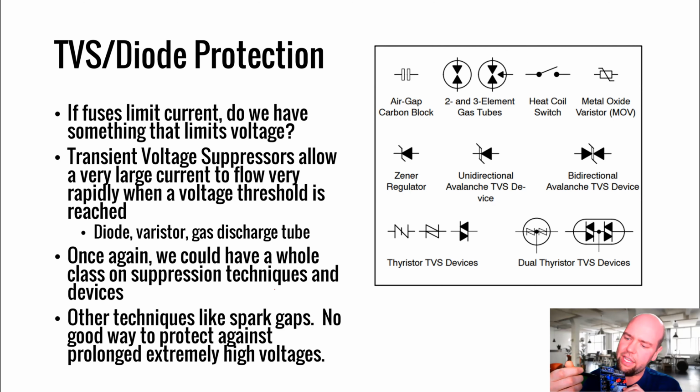Yeah, right here on this edge, right in between these switches, you can see these little fuses. I can't get it close enough, but these are PTC, positive temperature coefficient resettable fuses. These are fuses that, when you have too much current, get hot and only cool down once you resolve the issue that's causing the excess current flow. And then they reset themselves. So that's interesting.